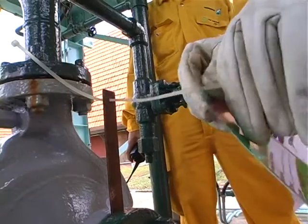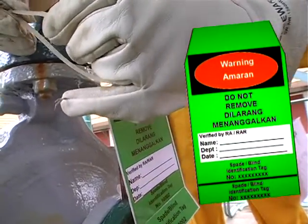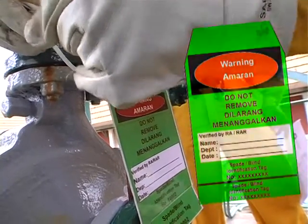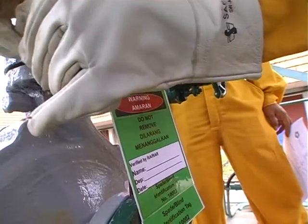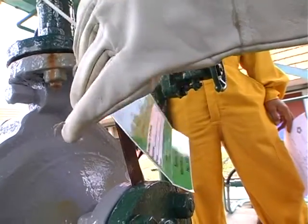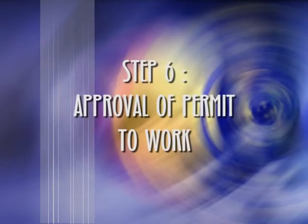AAR must place the green spade or blind identification tag on the installed blinds or spades. The green spade or blind identification tag number must be recorded on the back page of PIC. Step 6. Approval of permit to work, or known as the PTW.